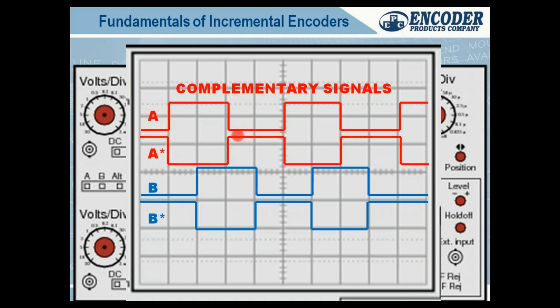In differential encoders, the receiving electronics are measuring the difference in voltage between the two channels to determine when a pulse hits. When I have just A, it measures at half the voltage. So if this is 0 volts and 5 volts for high and 0 volts for low, think of a 0 and a 1. If this channel ever exceeds 2.5 volts, once it hits 2.6 volts, my PLC is going to call that a pulse. So when I have that spike in voltage, it's a pulse.